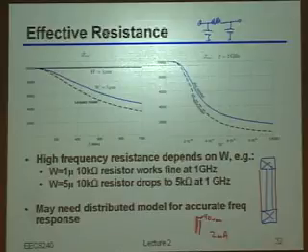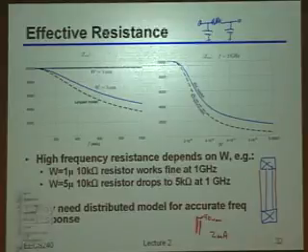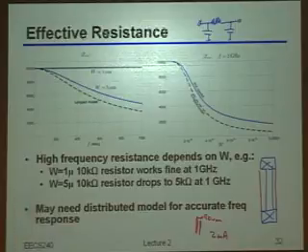which obviously gets into a nice positive feedback loop. Okay? So again, keep those things in mind, because indeed you'd like to make the resistors as small as you possibly can, but sometimes, because of the physical current you're shoving through it, you're not actually allowed to do that, and you will pay a penalty in terms of the parasitics. I also mentioned that if you really want a very accurate frequency response, you may need some sort of distributed model, but oftentimes even just a simple pi model like this will really do the trick.